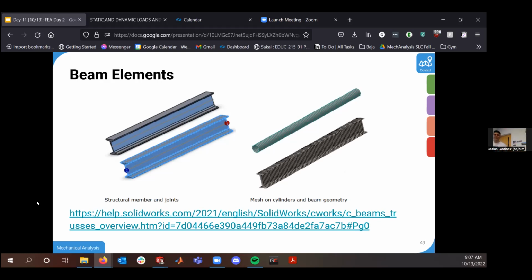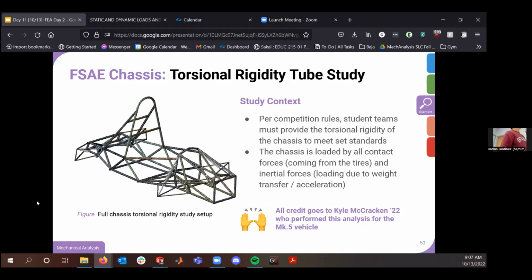And for now, a real world example, my better third, Colin. Okay. And I'm going to talk about an example for a beam element analysis. But before getting into that, why you might want to care about my different element choices: when you get to industry context, when I'm thinking about computation time and the affordability of my model, you'll see that solid elements are usually the last resort of options.